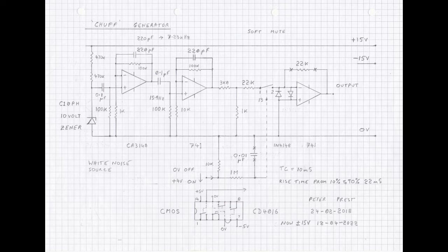Since I was not interested in hi-fi, I then fed this to an efficient digital speaker amplifier via an electronic switch controlled by the optosensor and the mixer circuit. The hiss was okay, but the starts and ends were too abrupt. To smooth these out, I experimented with one of the channels of a CMOS CD4016 FET switch and achieved a result which I considered acceptable.